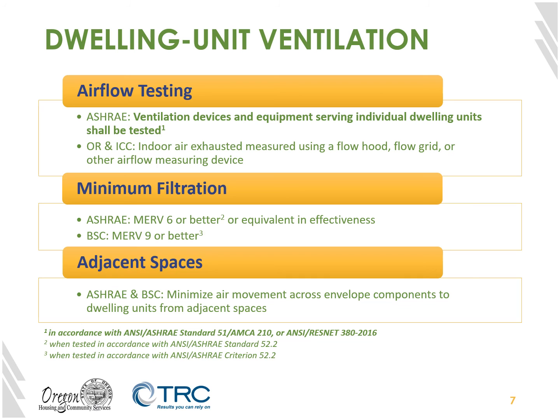Finally, these standards also mention the relationship to adjacent spaces and basically recommend a blanket expectation to minimize air movement across envelope components. This is the compartmentalization concept we discussed in Module 1 of this series. Use gasketed doors and air seal the wall assemblies between apartments.